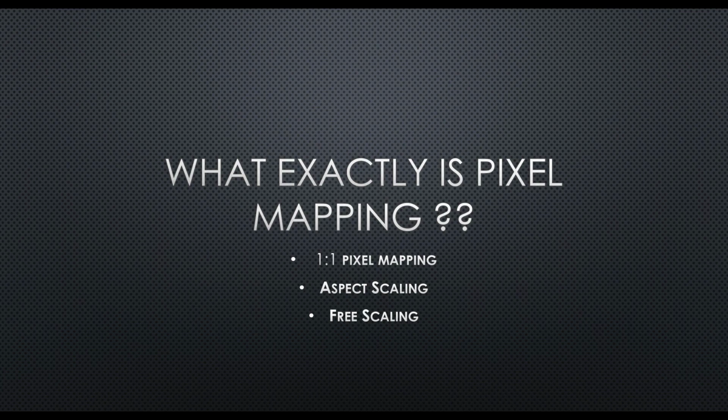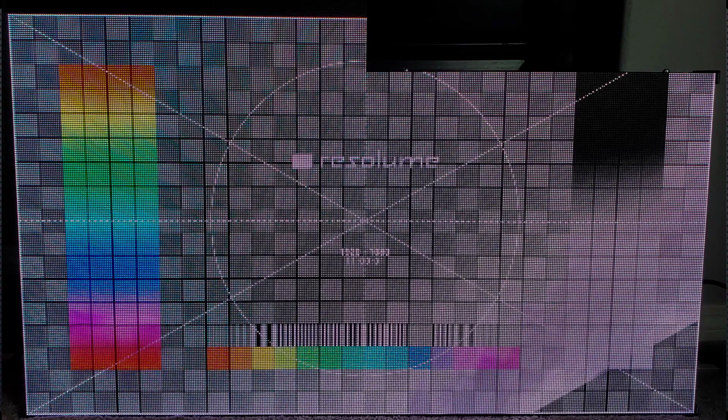Within scaling, there's aspect scaling and free scaling. Aspect scaling is basically scaling while maintaining your aspect ratio. So if your signal coming in is 1920 by 1080, it is a 16 by 9 aspect ratio. If your LED screen is not a 16 by 9 aspect ratio screen, then you're going to have to do free scaling, in which case you're going to manipulate the image, and it's probably not going to look good because it's going to be squeezed. You might make some faces stretched out, or squeezed in. While in aspect scaling, you keep the aspect ratio and just scale it up or down to fit your LED screen.